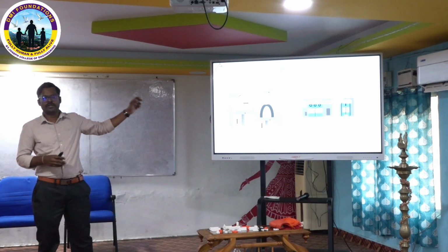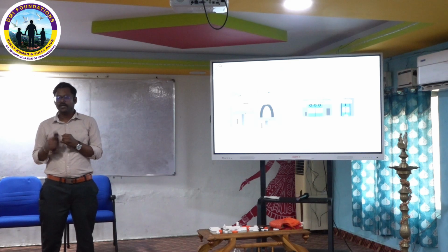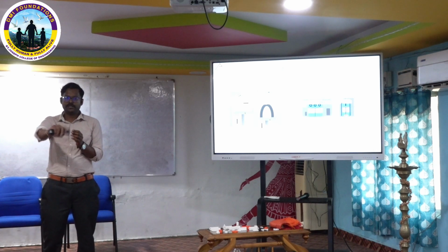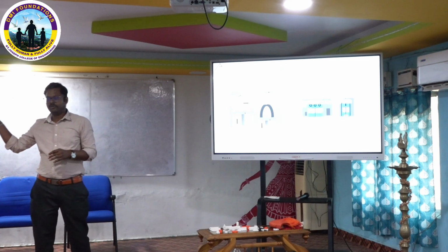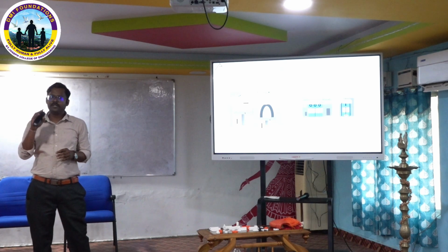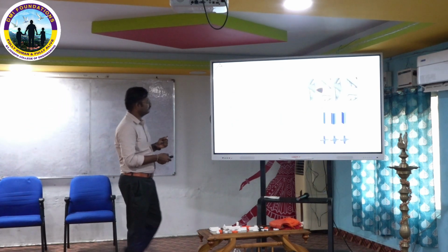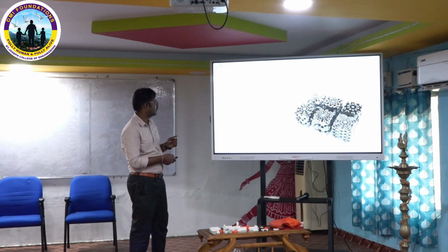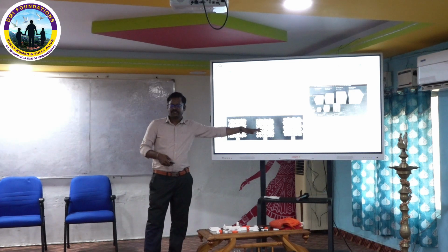But what we have to consider during fabrication is that we need to finalize the post-processing techniques. If we go with polymer-based post-processing, we need to carefully clean the powder. Before that, while finalizing the step dimension, we also need to consider what additive manufacturing method we are going to use. If powder-based, we need a provision to clean the powder. This is the kind of sample I am going to fabricate.